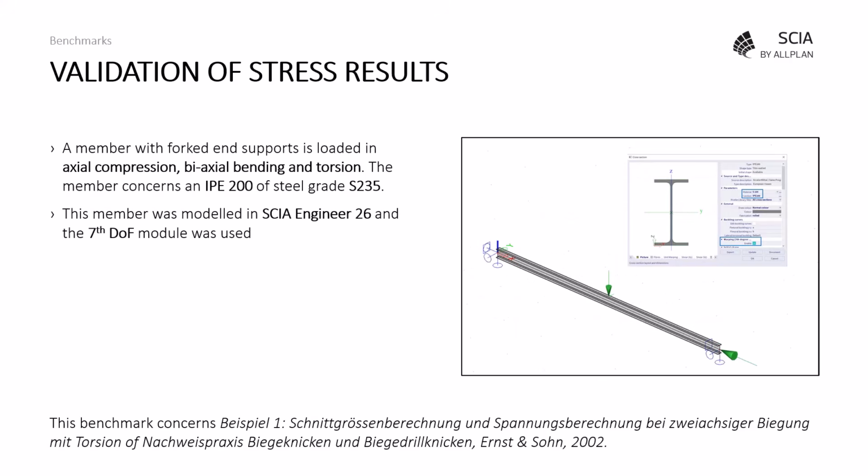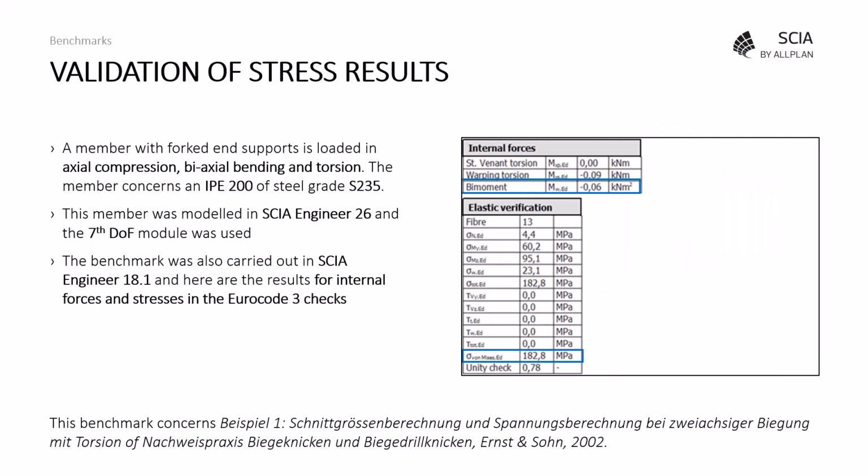So we have modeled this in SCIA Engineer 26, and we have activated the 7th degree of freedom. We have also carried out this benchmark in the past in SCIA Engineer 18.1, and we were able to have a look at the results in the detailed Eurocode 3 check for the beam.